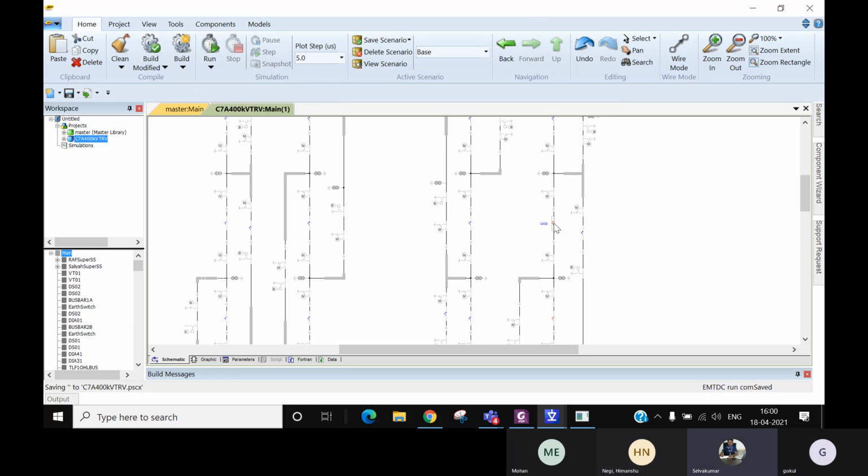Yes. Correct. So, you have asked a question that is close to that, but you have not really asked whether, when TRV is within the limit, it will stay within the limit or not. The question can be asked the other way also: is there any possibility that TRV is within the limit at the first maximum point, and is it possible that at the second or third peak it can cross the limit?